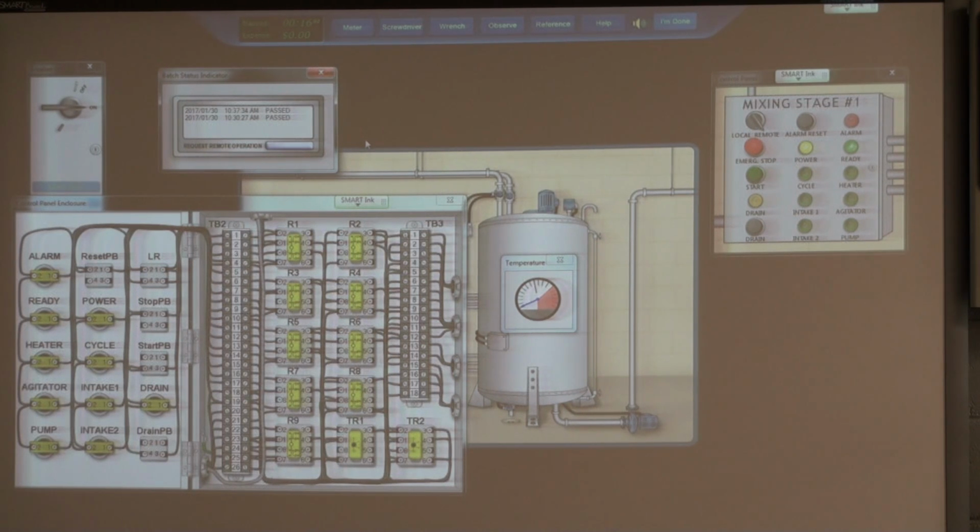R1 is, right? Yep. So 1 close. R4, R5. You can go down pin 1 and 8 and basically see which ones we're using. Now, they may not all be used. If they've got something tied to common, then we're using both contacts. We may not be using the normally open and normally closed side of both those contacts. But it's just a quick way of familiarizing yourself with some of the things that are in there.